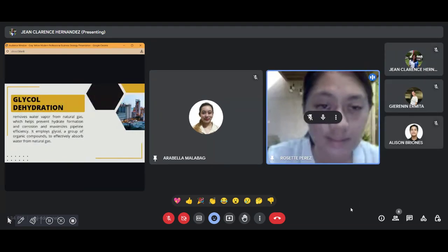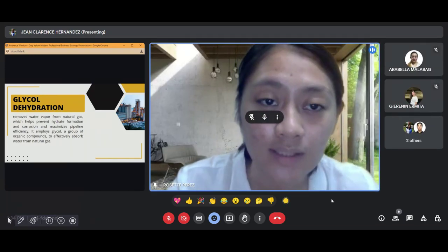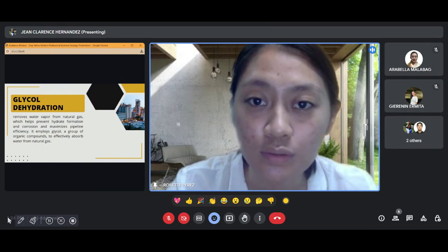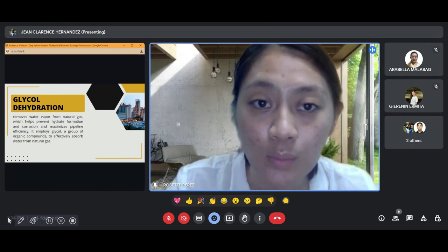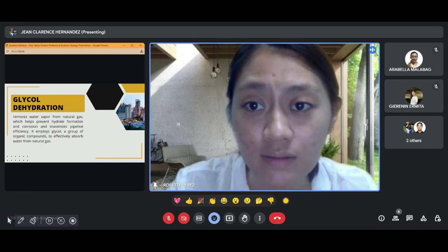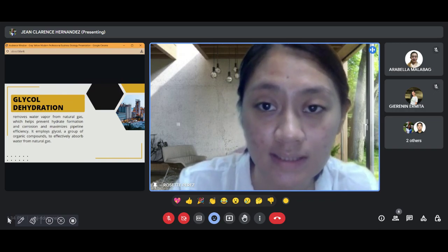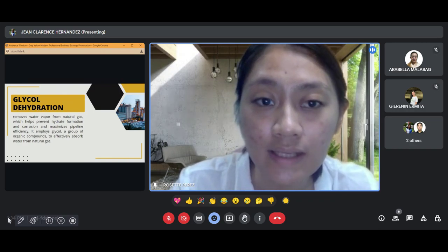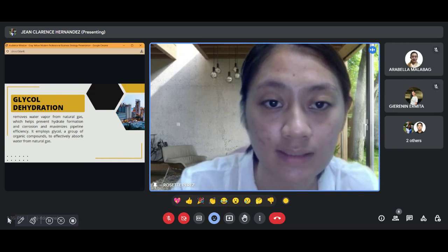I'm Rosette P. Perez and I'm gonna be discussing glycol dehydration. Glycol dehydration is a process used to remove water vapor from natural gas and natural gas liquids. When natural gas is extracted from the ground, it often contains water vapor, which can cause various operational issues if not removed. The glycol dehydration process employs glycol, a group of organic compounds, to effectively absorb water from natural gas.